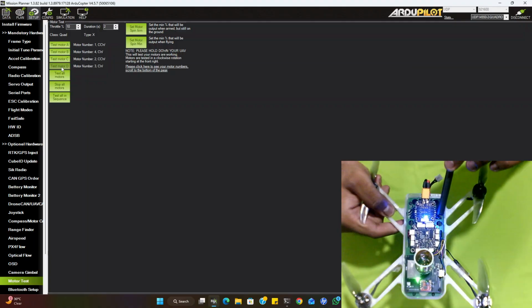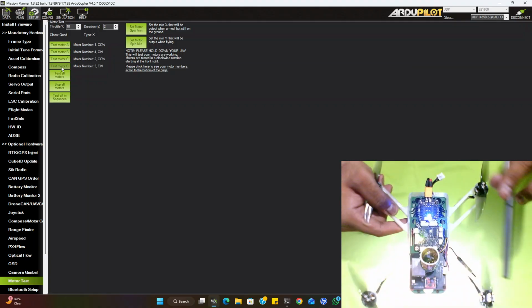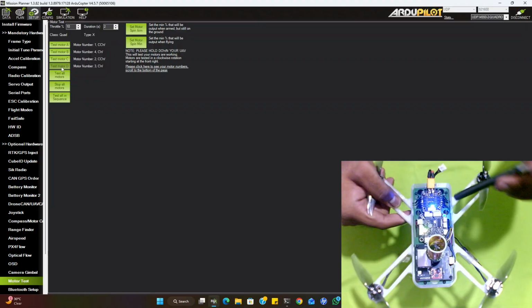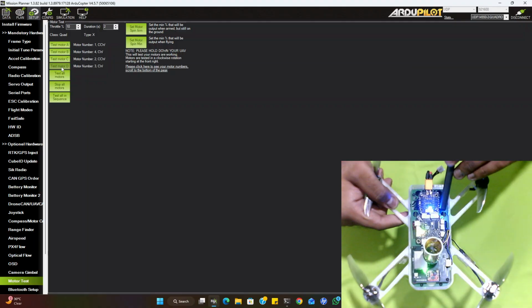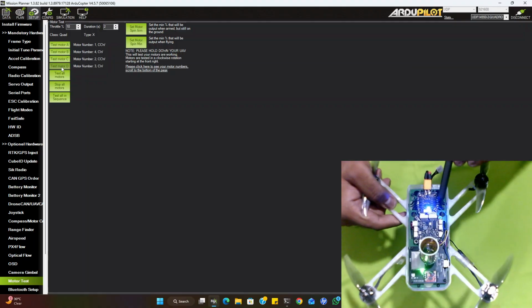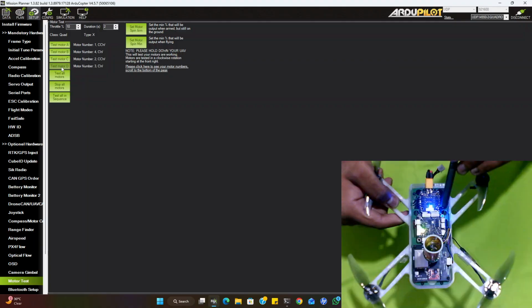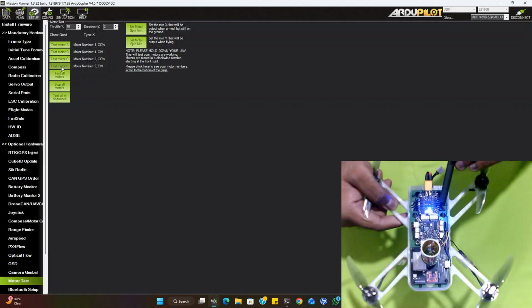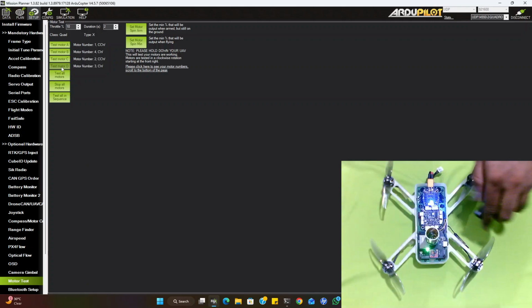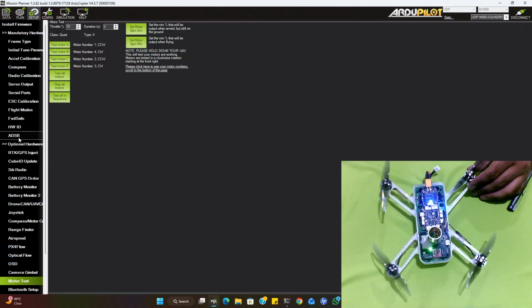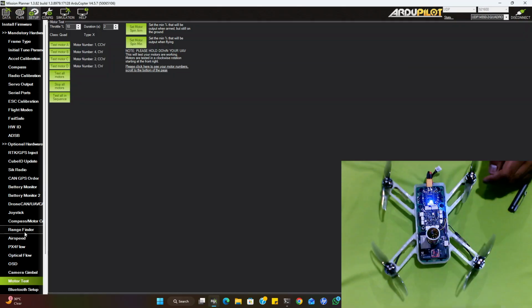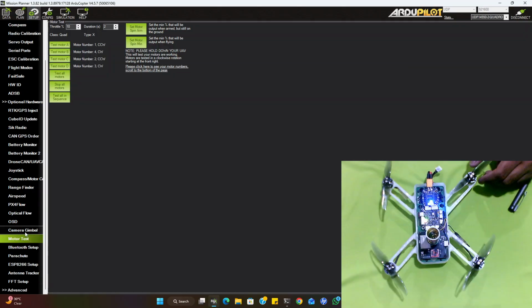If a motor is not in the right direction, you need to swap wires 1 and 3, like one to over here and three to over here. Just swap the 1 and 3 wires with each other, and the motor direction will be changed. So you need to check this before the flights. After finishing this test, your motors are almost ready, and you have the perfect data.